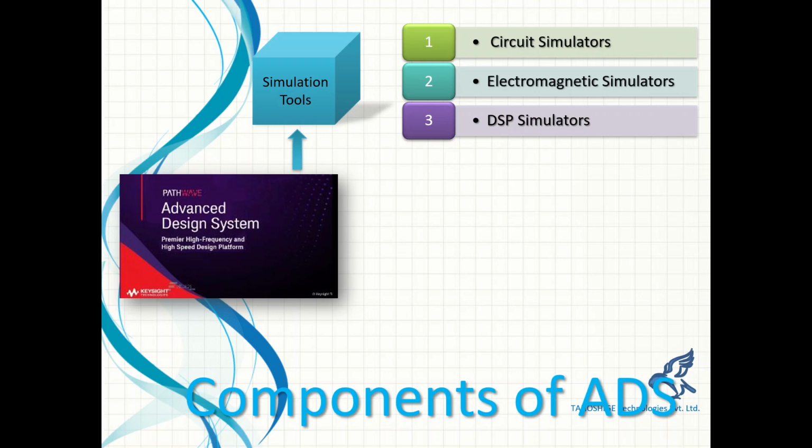You can also do this in frequency domain, like harmonic balance, which is basically developed from what is called Volterra series technique. Harmonic balance you can do, and then you can do a time stepped harmonic balance, which is called envelope simulation. Then there are certain modeling tools, like you can do X parameter modeling and simulation, right? So these are some of the circuit simulator related tools.